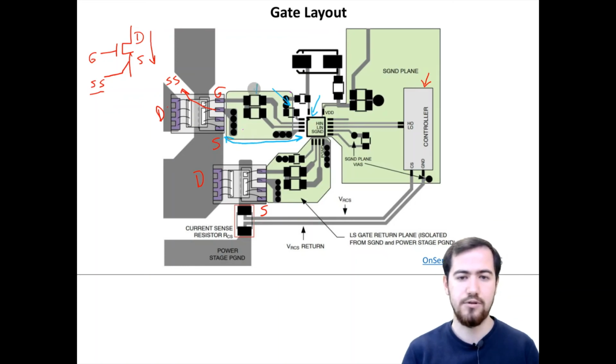Separate turn on, turn off resistors are included. Wide traces are placed to minimize the inductance. Moreover, for returning current, a copper region is placed on the bottom layer, and this bottom layer copper plane is placed just beneath the topside tracks. This is the way of minimization of inductance for the gate loop. And as you see, for the low side switch, this is also valid as well.